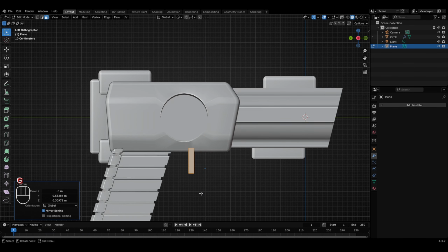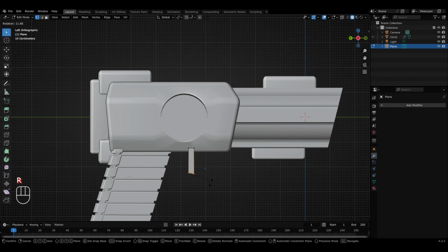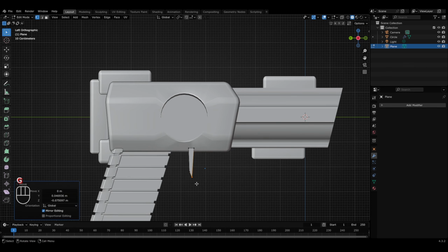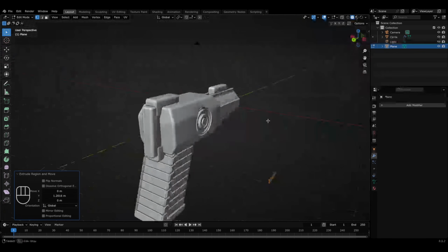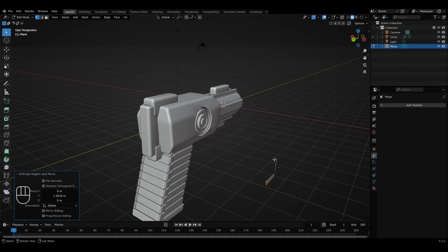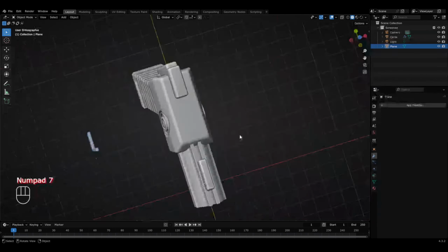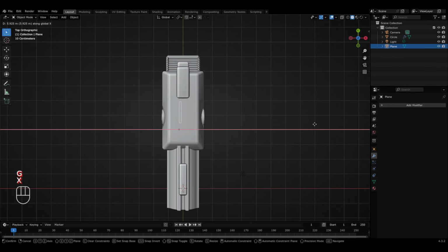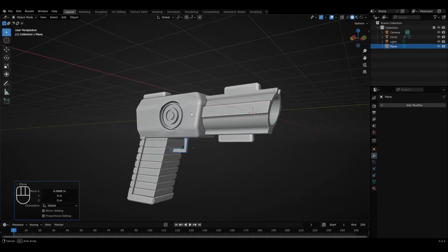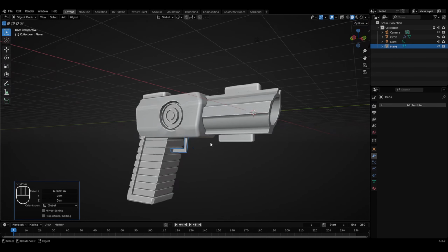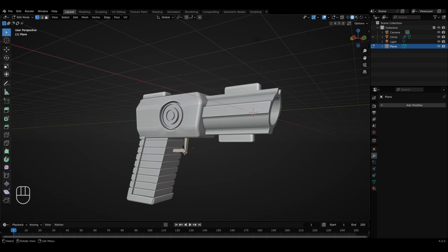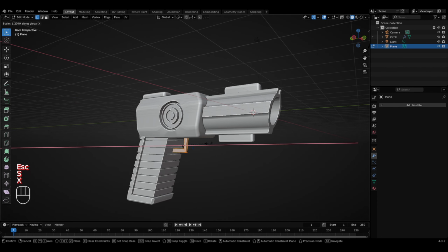Now I'll place it over here, then select these two vertices on the bottom. Let's rotate them slightly like this, adjust everything properly, and after that I'll press E to extrude it in the Y-axis like this. Currently it looks very simple, and moreover it's simply a plane, which means that we need to select all the vertices or the faces and extrude them like this to give them some thickness. After this, to fix its position properly, I'll move it in the X-axis like this and place it in the middle. Moving ahead, I'll change the angle, and over here I think that we should make it slightly thicker, so I'll press A to select all and we'll scale it up in the X-axis.